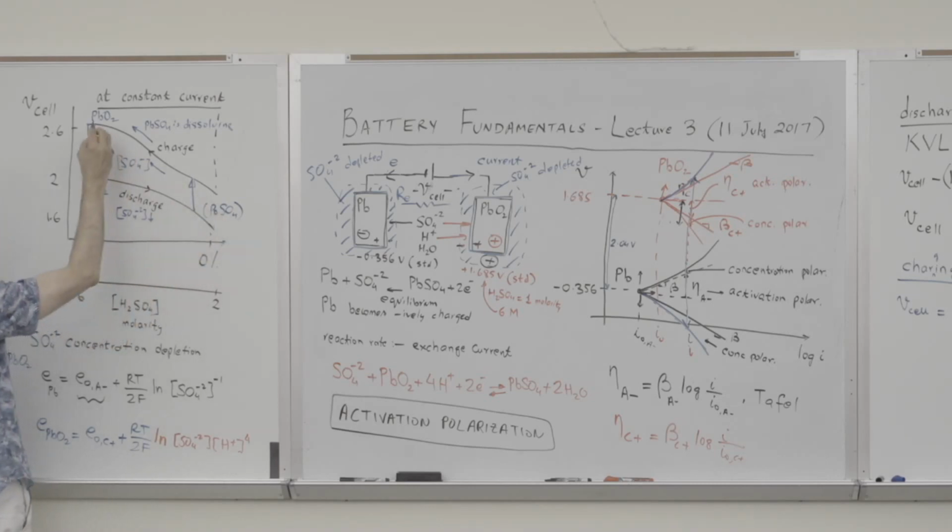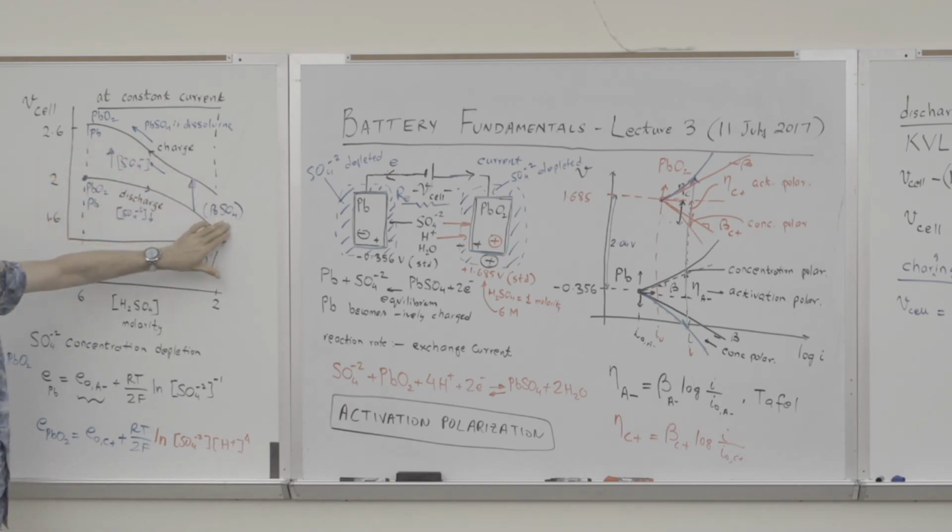You end up with lead oxide on the lead oxide electrode and just lead on the lead. So there is no lead sulfate over there. So in other words, as you're going that direction, you have more lead sulfate, which is resistive, voltage drop across that. As you go to the left, there's not much lead sulfate for that voltage drop.